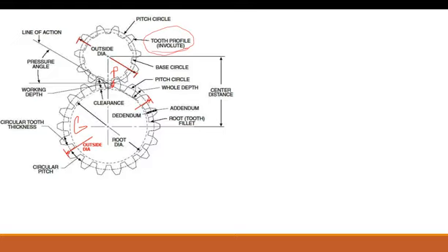So it's got this radius that's designed into the tooth so that it makes contact and maintains that contact over a longer period of time. So the transmission of the power from pinion to gear or gear to pinion is smooth. The gears typically won't disengage when you have an involute until the next gear has actually come into contact. That's one of the reasons why it's such an important shape in the gearing system.